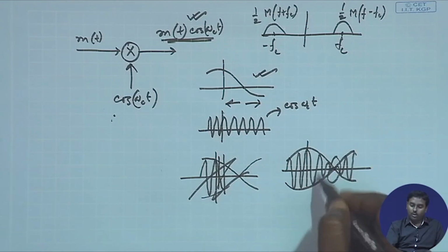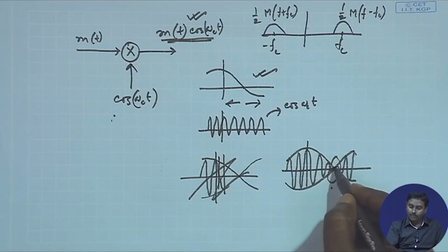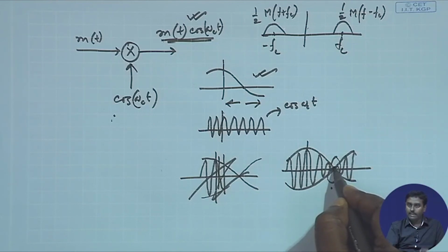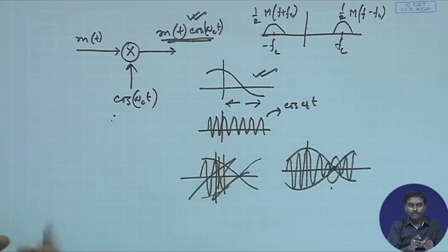The cos is going up to this point, it is positive, immediately after this point it will be negative. So in the phase of the carrier, what will happen? From positive to negative it immediately jumps. So there should be a 180 degree phase shift immediately, because the amplitude is going from positive to negative. Therefore, in the carrier phase there should be a 180 degree phase shift.